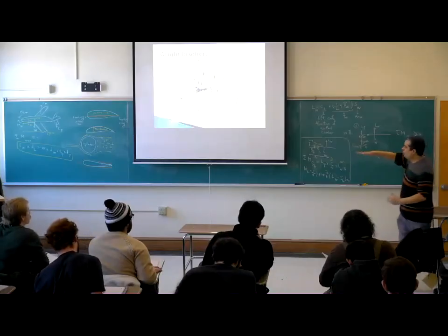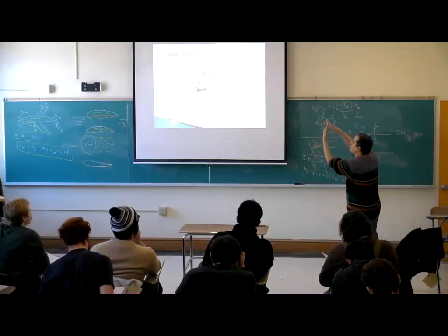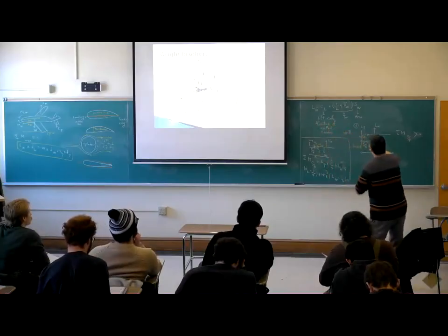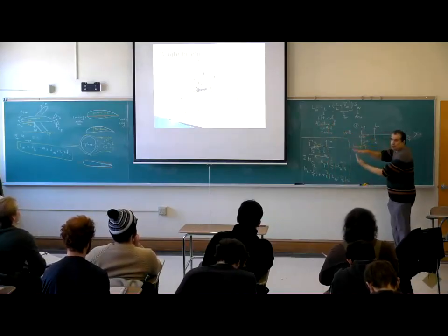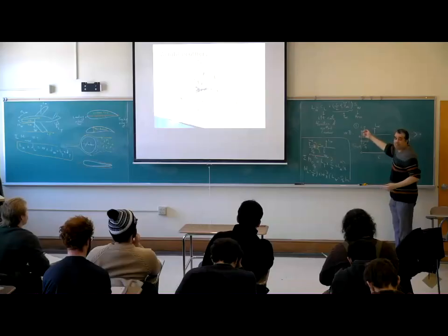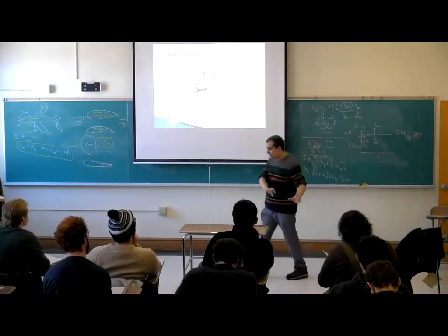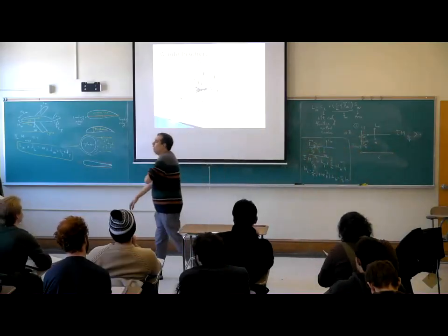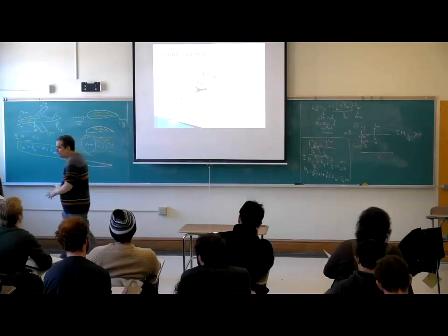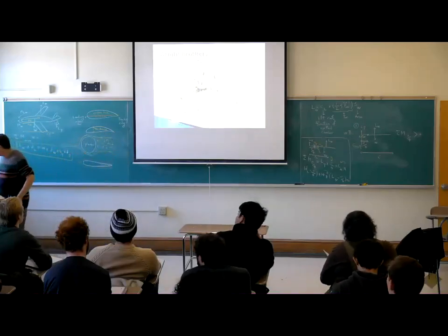If the moment should be 0, take a look. A gust wants to bring it up. The lift of the tail also wants to bring it up because it is positive. So I should reduce the lift of the tail such that the lift of the tail plus the lift due to the gust is the same as the previous lift.